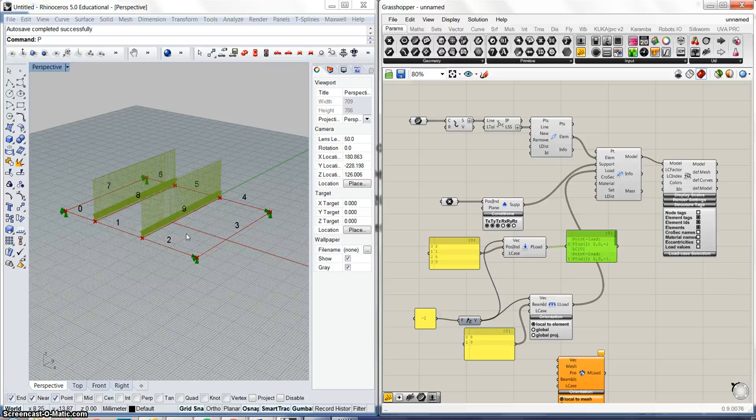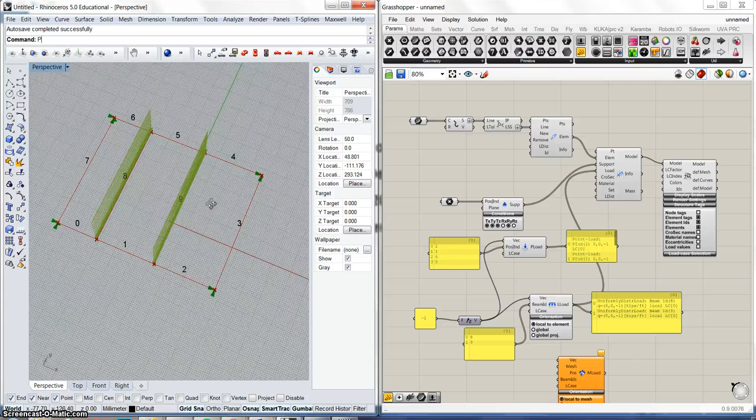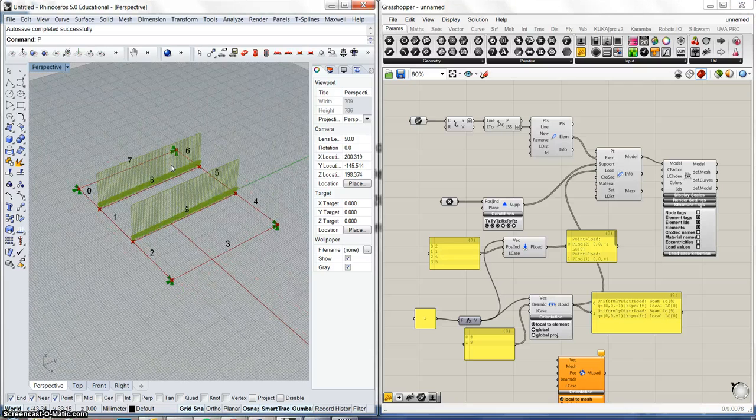So in total, when I had 4 of these, my total value was -4. The distributed load, on the other hand, is a load per linear unit. In this case, my units are set to feet because I need that for another class. Yours should be set to meters. But this is kips per foot. So this load is -1 kip per foot across the whole length of this beam. So this is a much greater load.